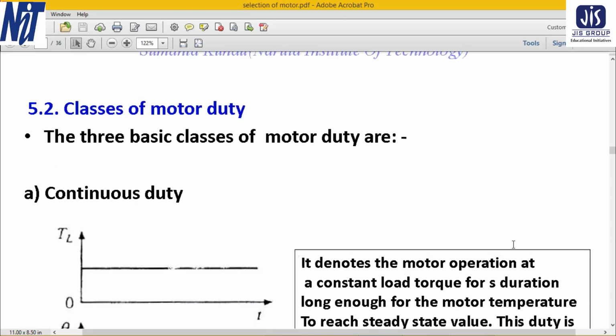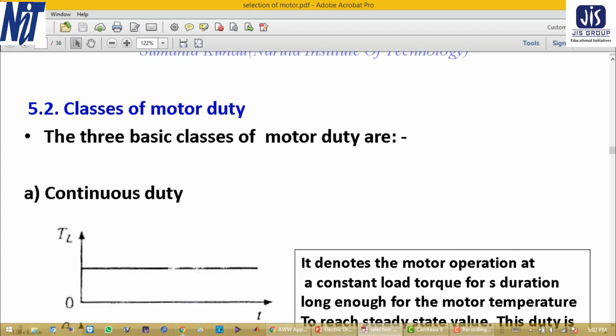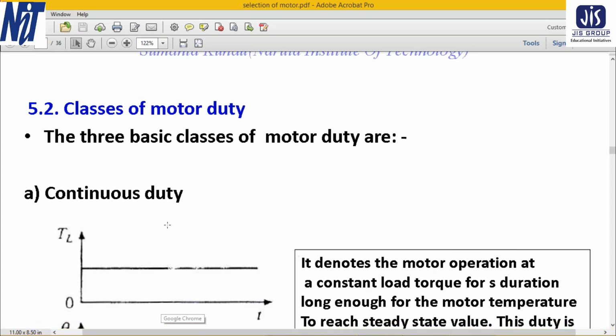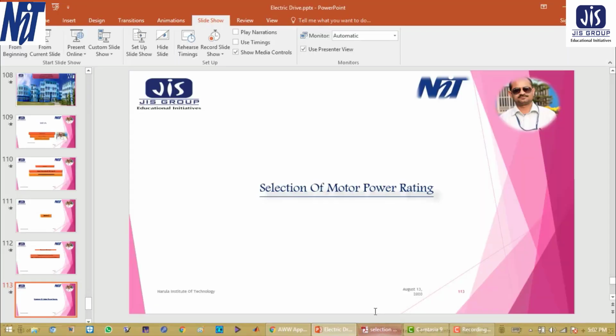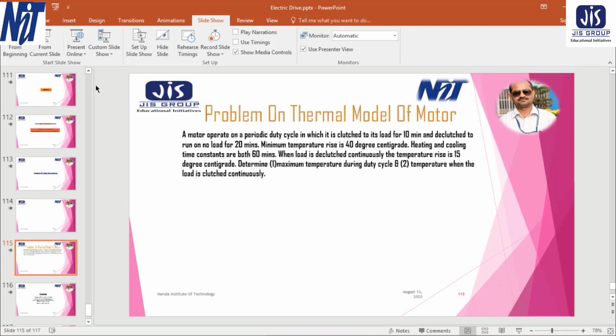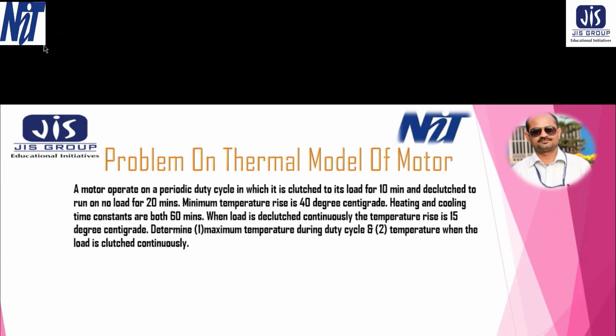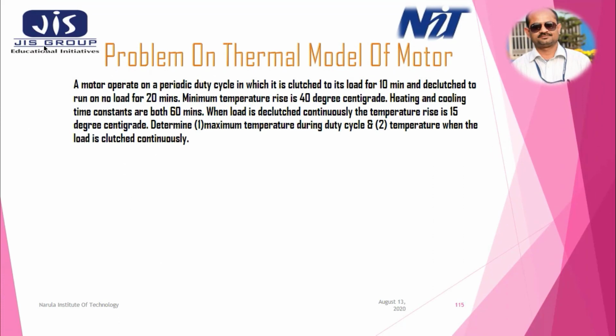Okay, so now I will solve one problem. This is my problem. A motor operates on a periodic duty cycle in which it is clutched to its load for 10 minutes and then declutched to run on no load for 20 minutes, and the minimum temperature rise is 40 degrees.